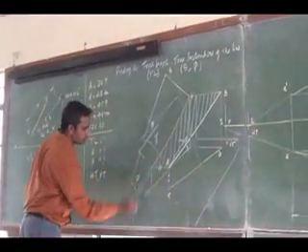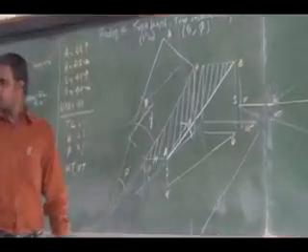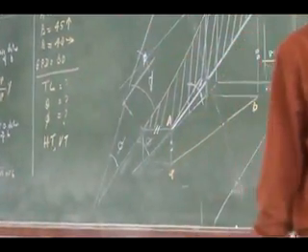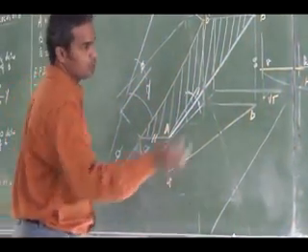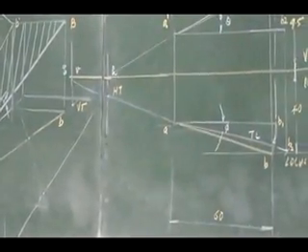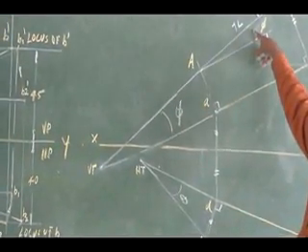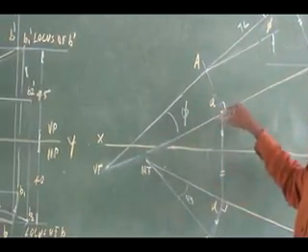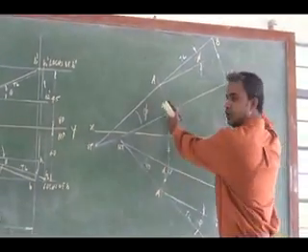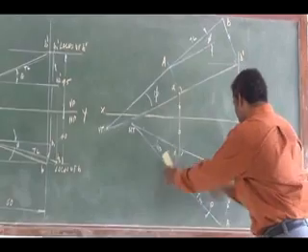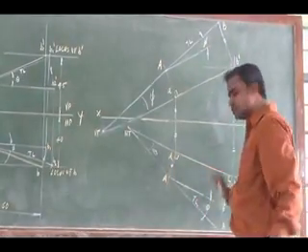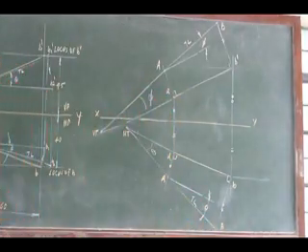This is my phi. The actual original line was this, this is phi, so the same phi angle I can measure. The same theta I can measure here. This is going to be my theta, the overall angle, and this is going to be my phi. That's what I have measured here. You need not extend it, you just measure. You can draw a parallel line to the front view; the inclination of the true length line with it is phi. You can draw a parallel line to the top view; that inclination is going to be your theta. Right. Move on to the next problem.